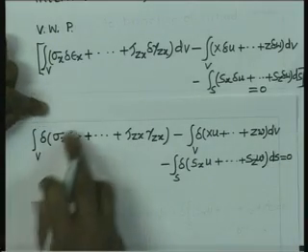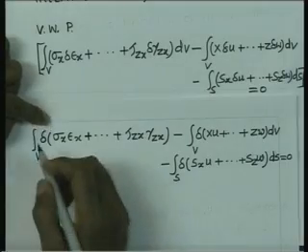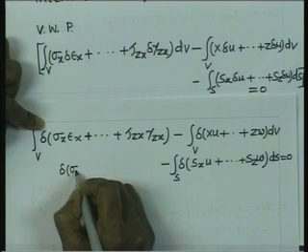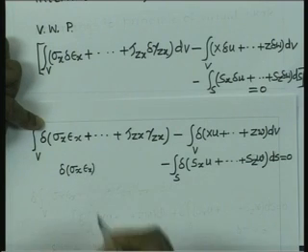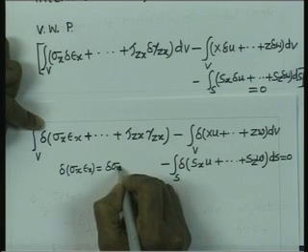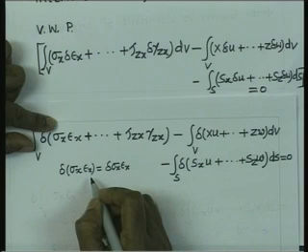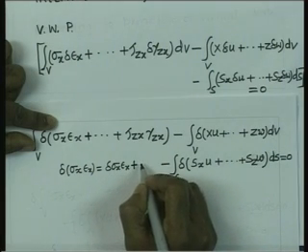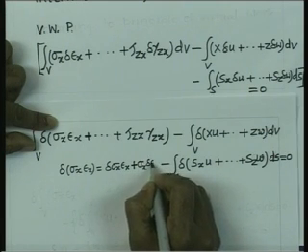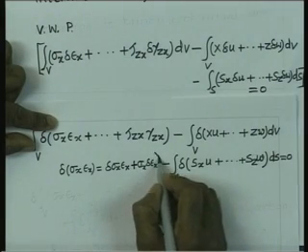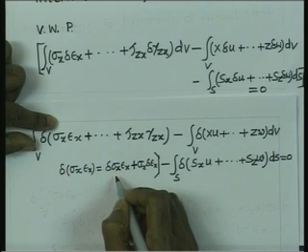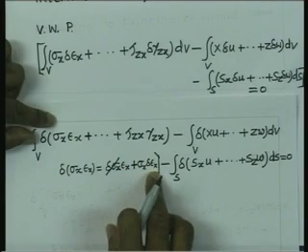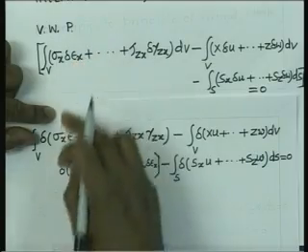So, therefore, we can take this delta out. This is because of the fact that this is a variational symbol, and if we have variation of sigma x multiplied by epsilon x, this is nothing but delta sigma x epsilon x. It is like differentiation of a product of two functions. We can write first differentiation of the first keeping the second constant, and then we can differentiate the second keeping the first constant. So, that is the way we can do. Now, in this case, since the stresses are constant, sigma x, sigma y, sigma z, this variation is 0, therefore, this product is 0, and hence this quantity is equal to sigma x into delta epsilon x. That is what has been made use of in writing the expression from this to this step.